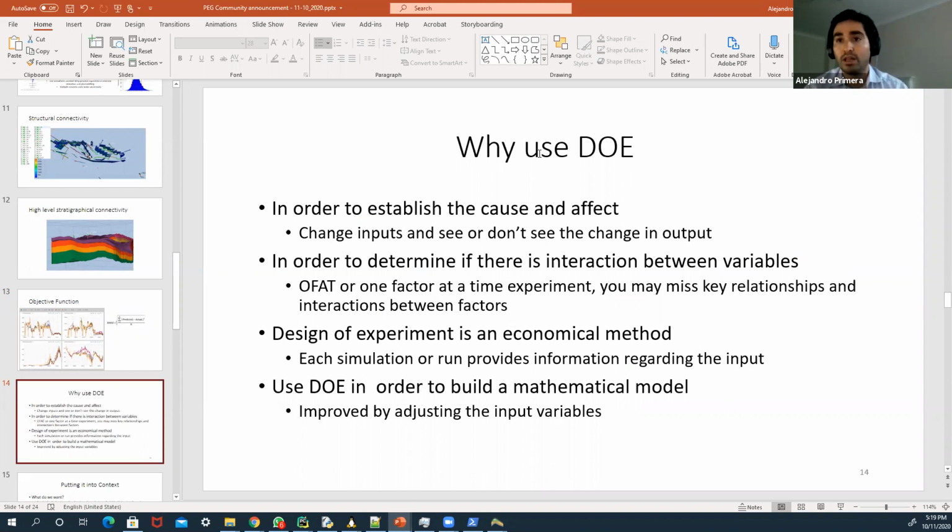You can do a multiple level objective function, and whenever you have real data that you have measured, and your simulator is able to come up with a result for that piece of data, you should write an objective function. So the well level is obvious in some fields where you are actually measuring the production per well.